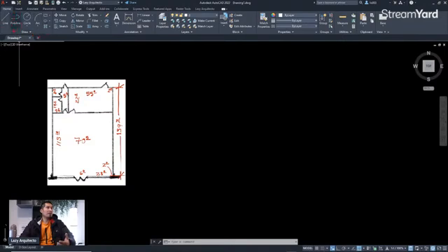This is called a panel, and it's on the Home tab. These are called tabs. If I already have a drawing here and I need to edit or modify, I can go to the Modify panel, so I can copy objects, scale, rotate objects, and so on. Again, all of the tools are organized here.